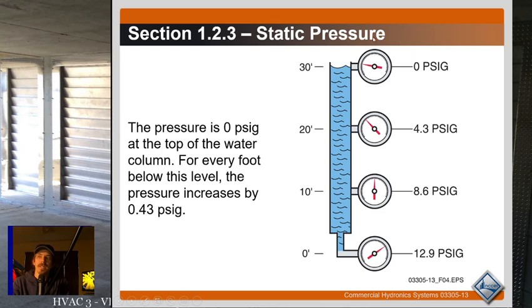Otherwise, your pressure at the top is at 0, and you're going to introduce air into the system, most likely, because you're going to have air reliefs and stuff like that at the top of the system. Those air reliefs will just be at 0 or negative pressure because of the outside air acting on the system, and you'll introduce air. So you just have to make sure you have enough pressure to fill to the top. So that's where we get that 12 psi from.